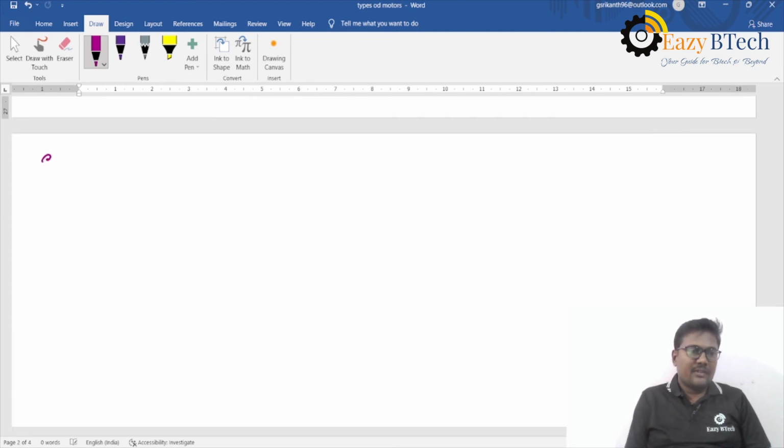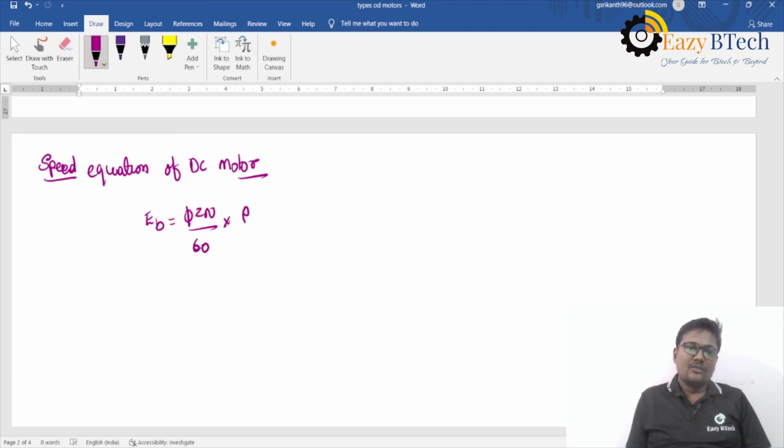And what is the speed equation? So the speed equation of a DC motor, generally the back EMF EB is equal to phi Zn by 60 into P by A. Once design is over, P is constant, A is constant, Z is constant, 60 is also constant.